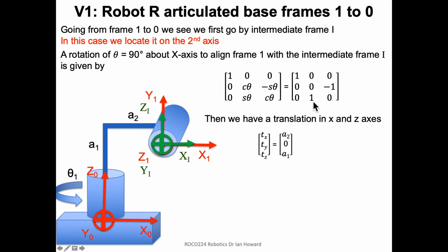So that's doing it just by thinking about inspection. But as I said, if you want to do it and say, look, how do I get this frame into that frame by rotation? You can see that it's got to be rotating round the x-axis. Then the y goes up and the z comes out. You can also do it that way. Then you can just put it in your formula and put 90 degrees in here. It's positive 90 degrees though, don't forget, right? And that gives you the same result.